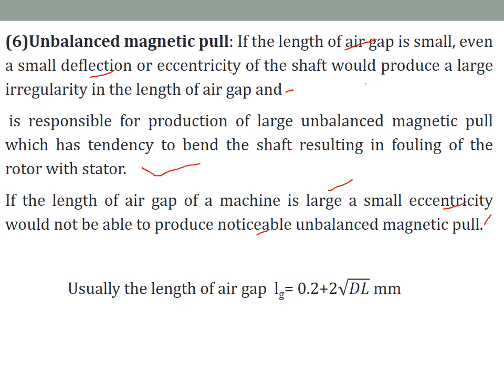It will give a jerk, because of which the shaft starts bending. When the shaft bends, the rotor may touch the stator. That is called fouling of the rotor with the stator. Once it touches, the rotor becomes jammed and the winding may burn.